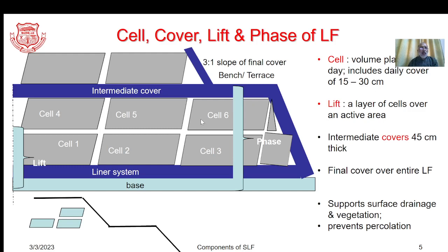Whereas over the days, the entire area of this particular sanitary landfill will be covered with a number of cells, and such a number of cells over the active area of that landfill would be considered as a lift. So these cells are resting on the base through the liner system. Already you know about what that particular liner is.